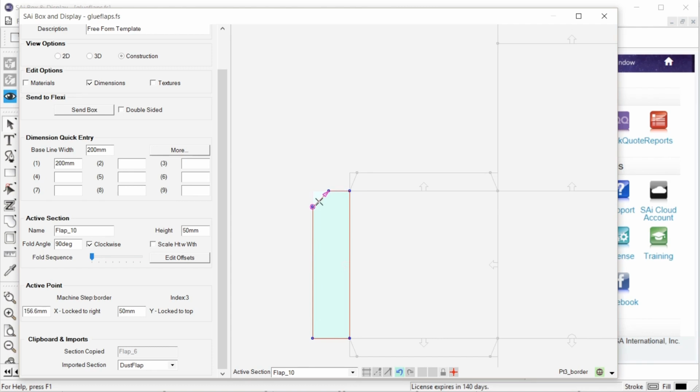You can adjust the chamfer by sight. Or you can hit the period key, which we will do to open the corner dimension dialog. Set the dimension to 30 mm and click OK. Now that you have the first corner chamfered, you can use the Ctrl-R shortcut keys to repeat this operation. Most of the freeform procedures can be repeated using these shortcut keys.